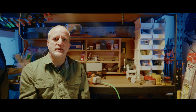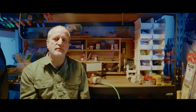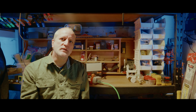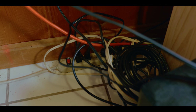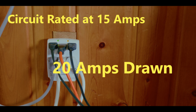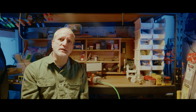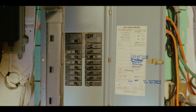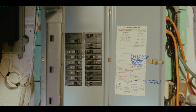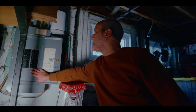Wire connections must be rated for the amperage being drawn. You must be careful if a device will draw more current than the wires will allow. If you plug in too many appliances to a 15 amp circuit, for instance, and they're going to draw 20 amps to run, then you must have some system to protect the wires, otherwise they'll overheat. Typically this is done by circuit breakers, which will only allow a certain amount of current to flow through the wires before they trip. That will save the wires from overheating and causing potential fires.